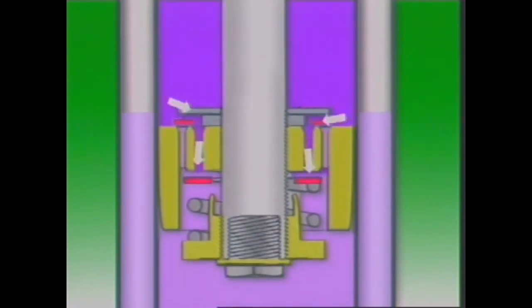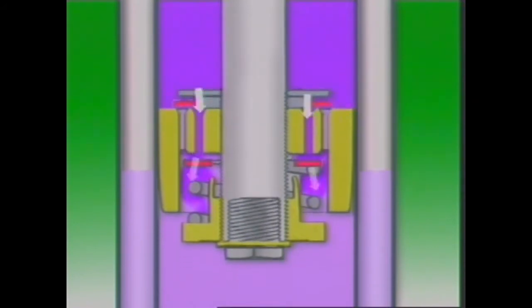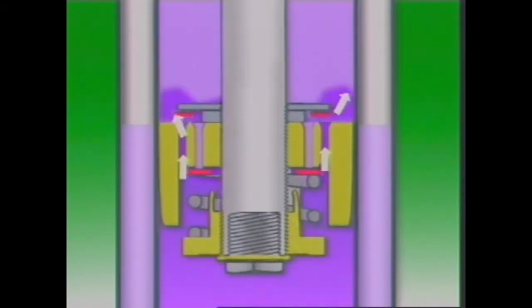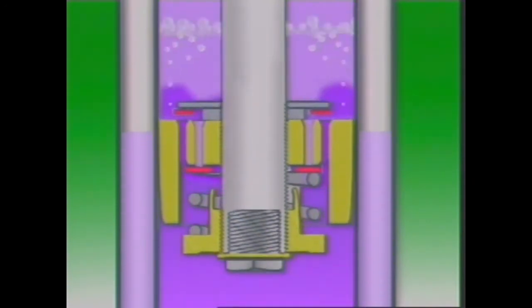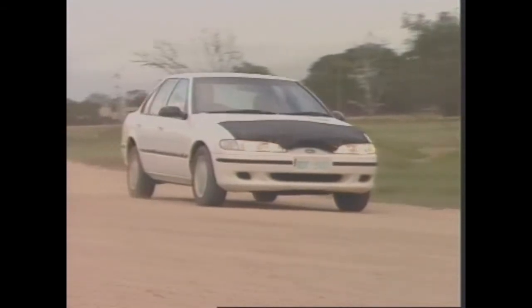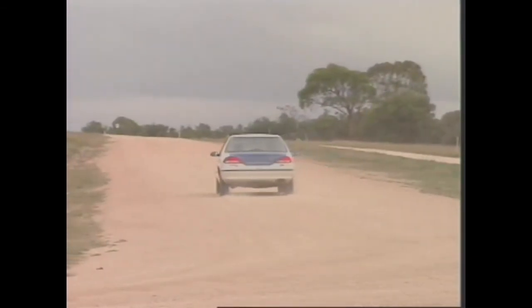Aeration occurs because of the high velocity of the oil as it passes through the small passages in the valves. If the velocity is high enough, air dissolved in the oil comes out of solution as small bubbles and forms a foam. Aerated oil has a certain amount of compressibility, so it is unable to provide the dampening force previously achieved in the non-aerated condition. The performance of the shock absorber is thus considerably reduced. This effect is called shock absorber fade.